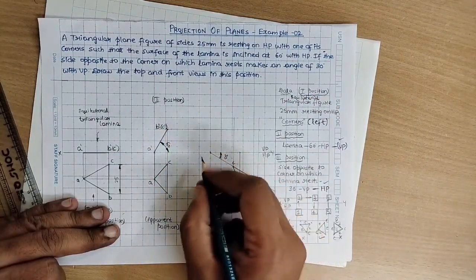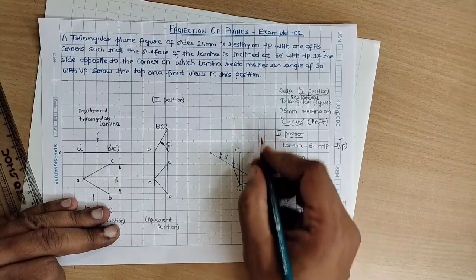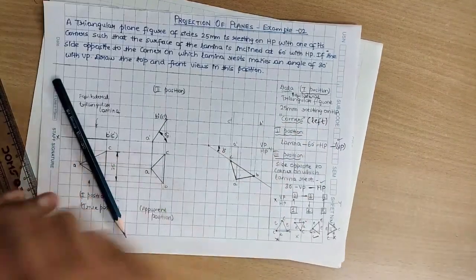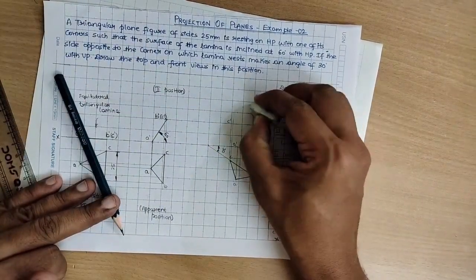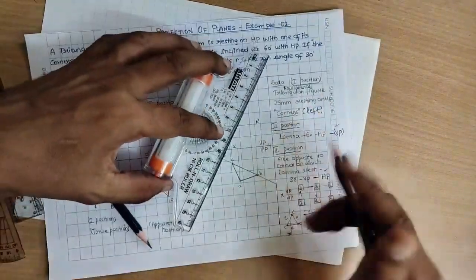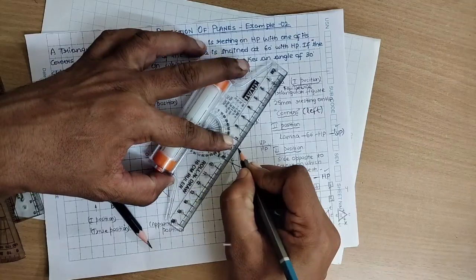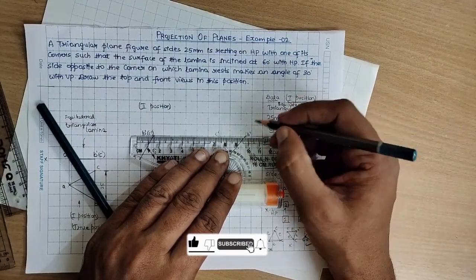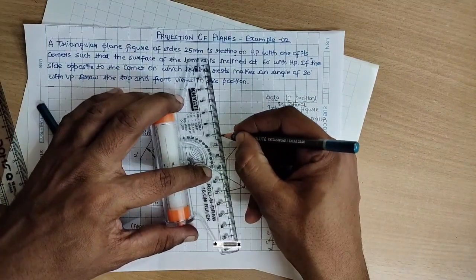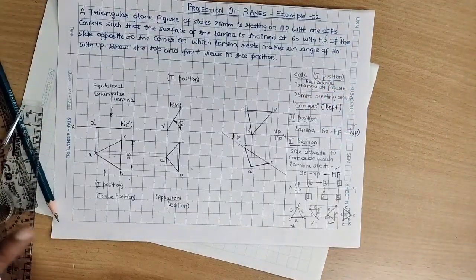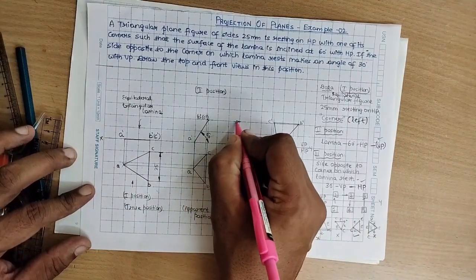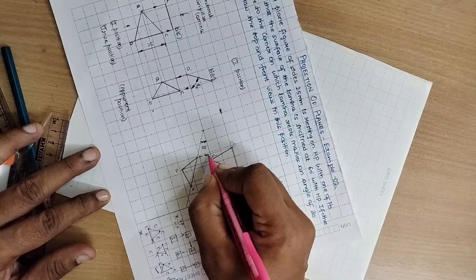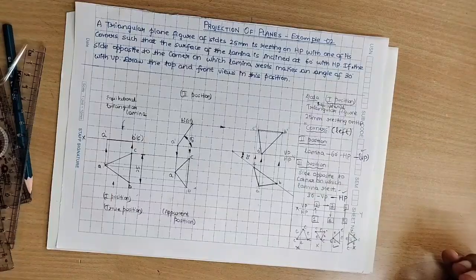Projection line from point A and A, this would be the point A dash. Similarly from B and B would be the B dash. Similarly this would be the point C dash. Any extra projections if drawn, we can remove them. Make use of scale. Draw a line connecting from A dash to B dash, B dash to C dash. B dash to C dash should be on the same straight line. C dash back to A dash. This would be the solution. Show the flow of the sketch. This would be the final solution.